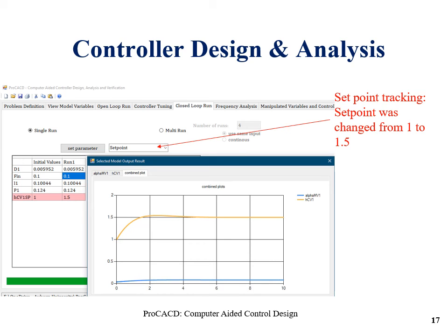So here you can see the yellow line, the yellow represents the set point change of the control variable, and the blue line represents the valve opening, which it is trying to adjust so that the new set point is maintained with respect to the control variable. You can clearly see that it's performing very well with respect to both disturbance rejection and set point tracking.